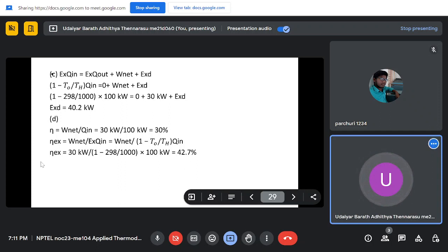As you can see, your cycle is operating at close to 50% of the efficiency of the Carnot cycle. So your cycle is about 40% efficient with respect to the Carnot cycle. That's what the second law says; it's just a comparative exergy. If this is 100%, your cycle is the best cycle, it has reached the Carnot efficiency. You cannot go more than that.